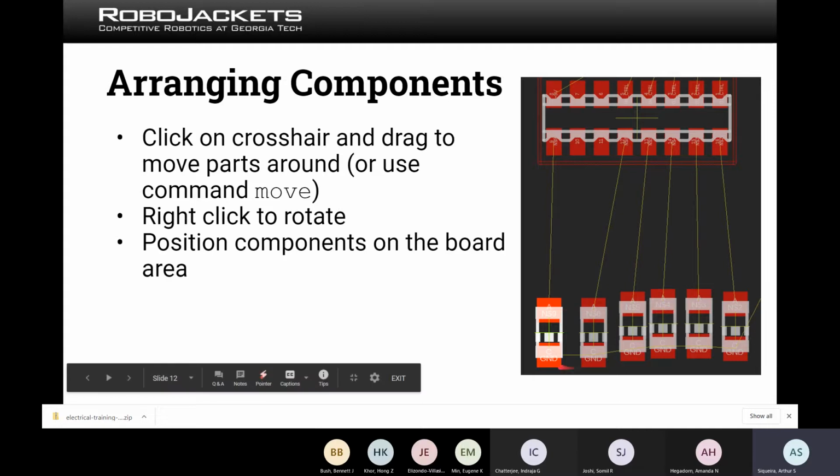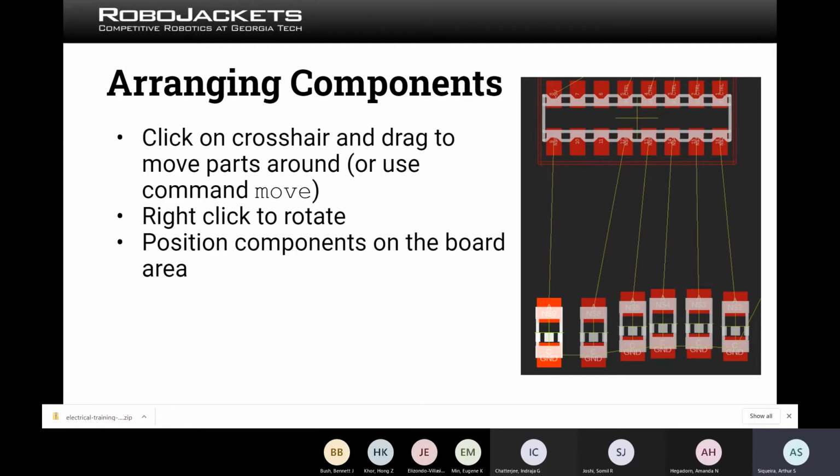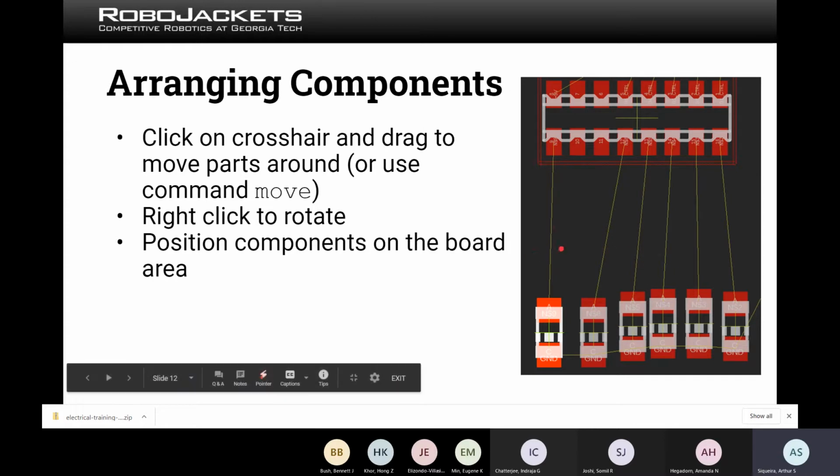For instance, you have a bunch of grounds in here, and you notice that this ground will try to create the air wire to the closest ground, and the same in here. But this is just a user-friendly indication tool, showing you where the nearest signal is that you should be connecting. So yeah, those are called air wires.